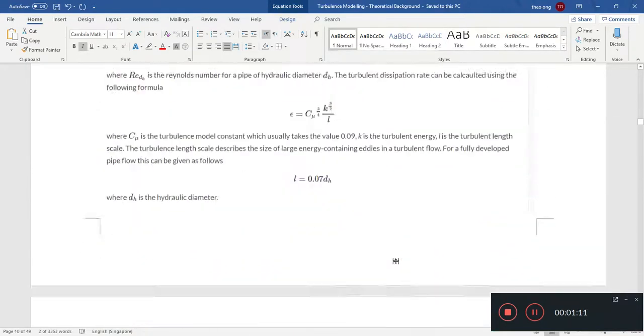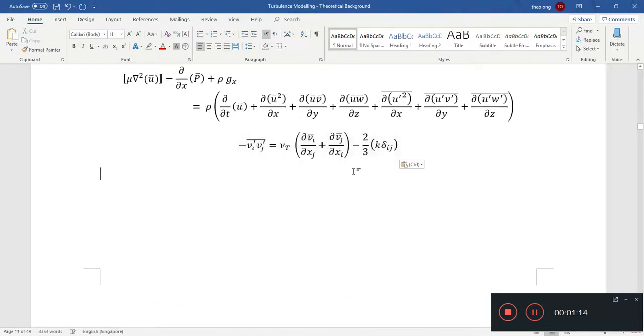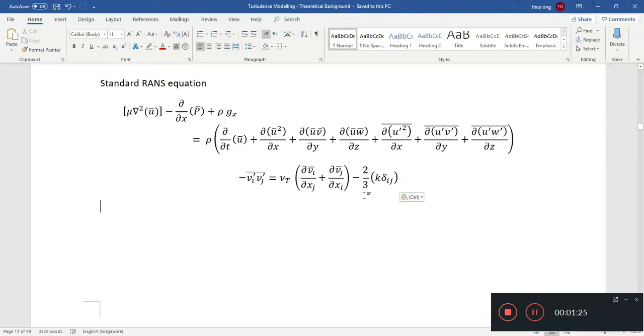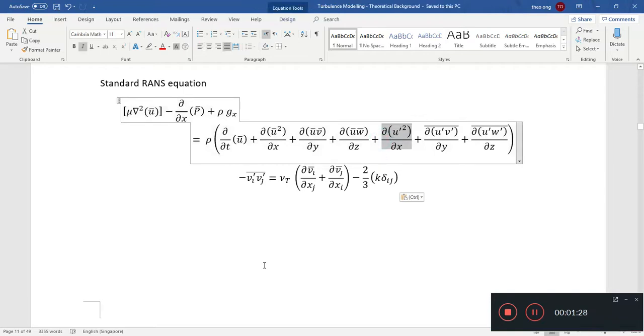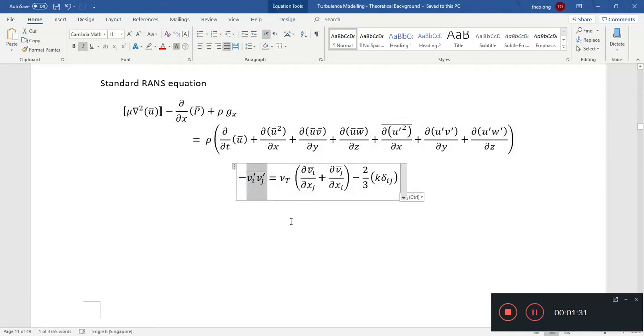So this is how we do the closure problem. Remember that when we do this Boussinesq relation, we represent this closure model this way. Remember, this is Einstein notation. I'm not going to go through Einstein notation again because I went through it before very extensively. And this is the Kronecker delta, which again, if i is not equal to j, that is 0. If i equals j, then the value is 1. So that's the Kronecker delta, and all of this is in Einstein notation.